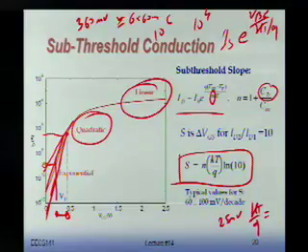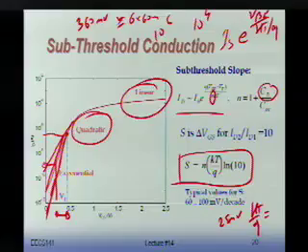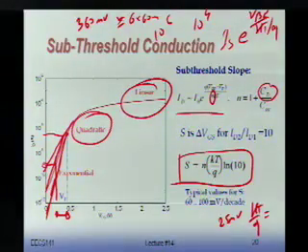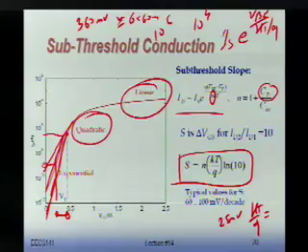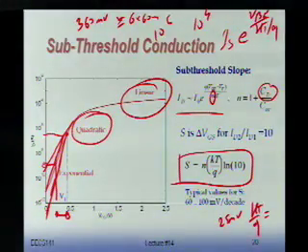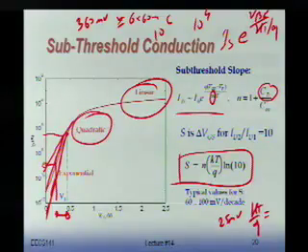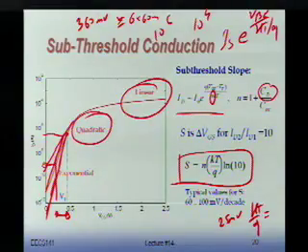So leakage current has now become maybe 30% of the power dissipation in some of the chips. If you don't do anything to fight it, you might end up with a big fraction of your power dissipation just doing nothing. So that's not a very good idea. And people have been thinking very hard to deal with that. But it's something you should be aware of, that leakage is a result of the subthreshold conduction and is a direct result of the threshold reduction.